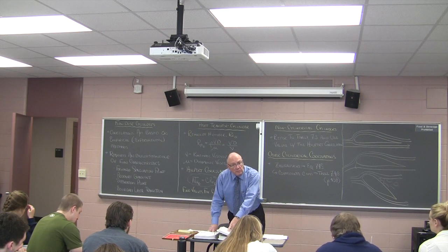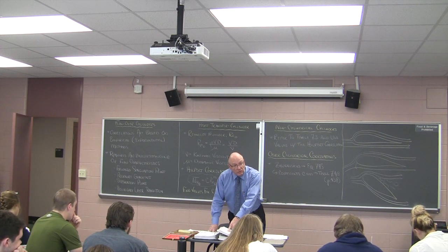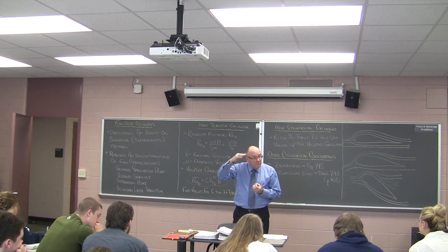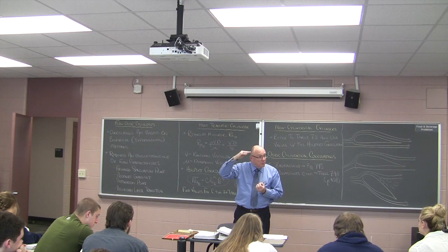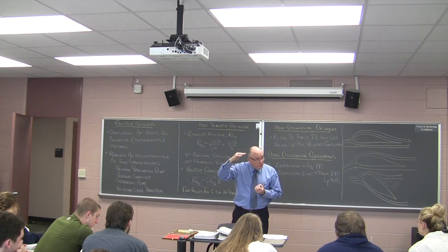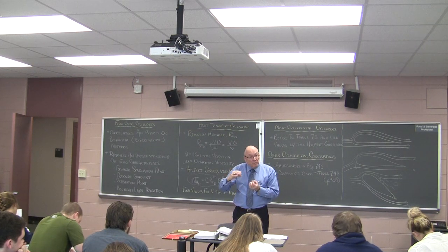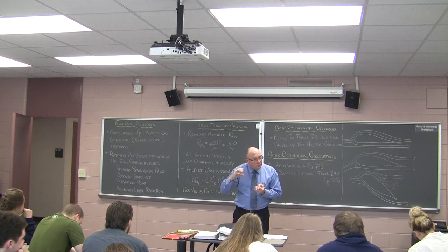That is the Prandtl number for the fluid properties flowing around the cylinder evaluated at the surface temperature. So you have the Prandtl number and the Reynolds number evaluated with the properties of the flow at the free stream temperature of the fluid. And then you have this other Prandtl number in that ratio, which is based on the surface temperature. That's the way Zukauskas did it.